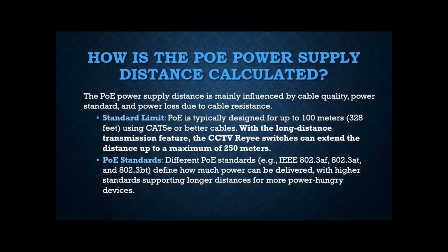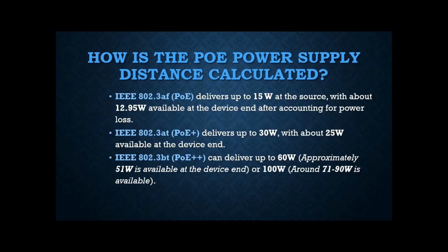So with different PoE standards such as AF, AT, or BT, this defines how much power can be delivered, with higher standards supporting longer distance for more power-hungry devices. So this is very important to take into consideration.